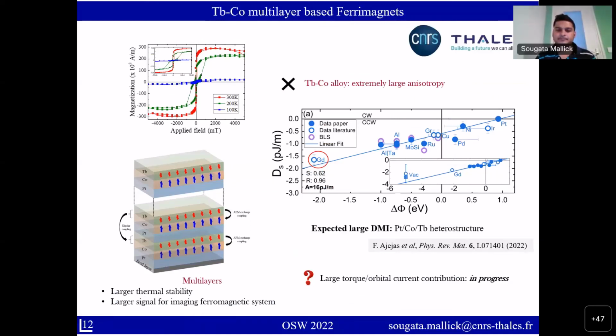Also, you have shown that the pulse width of the pulse you are using is up to 5 nanoseconds. So what is the rise time and fall time of the signals that you are using, I mean, of the pulse generator? The rise time was around 600 picoseconds. Okay, so with 600 picoseconds, you are able to stabilize a square pulse of 5 nanoseconds.